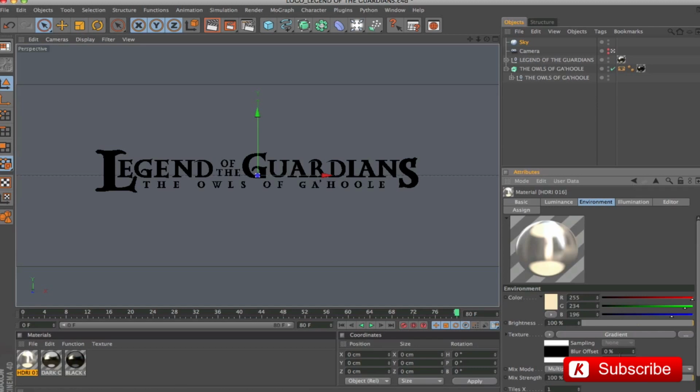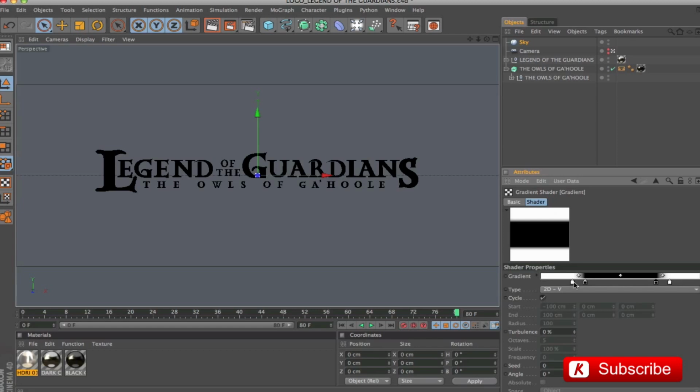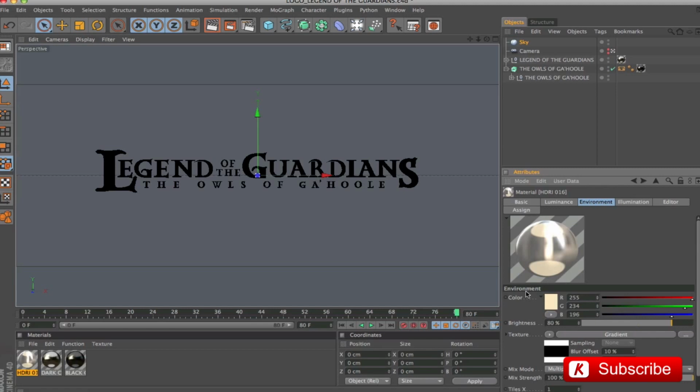Insert 10 value on blur offset and scale, and 80 on brightness. This gradient is used to create more reflections on the top and bottom of the chrome material. In this case, it has feathered edges. If you want more sharp edges, you have to change the distribution of colors in the gradient bar.